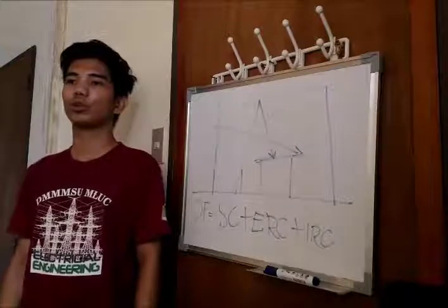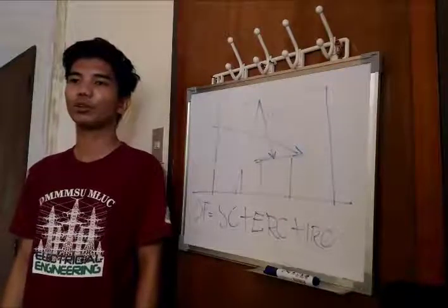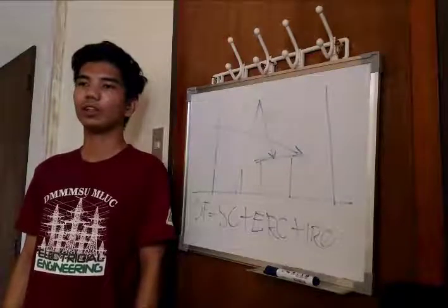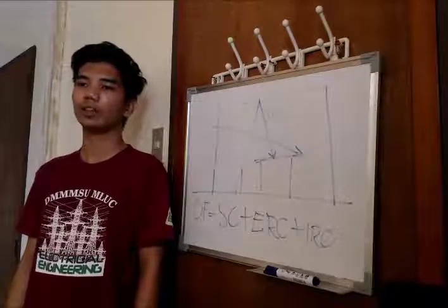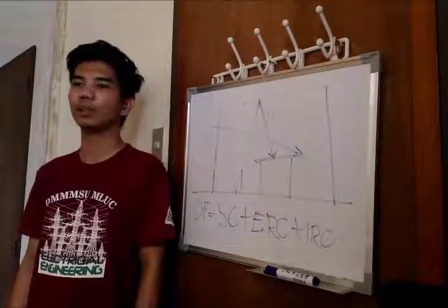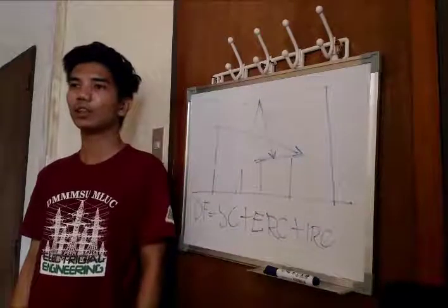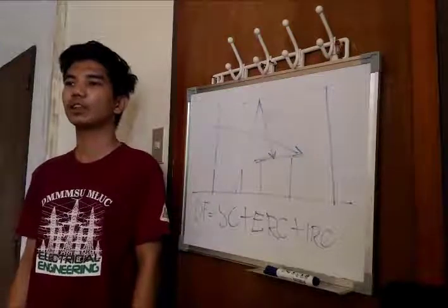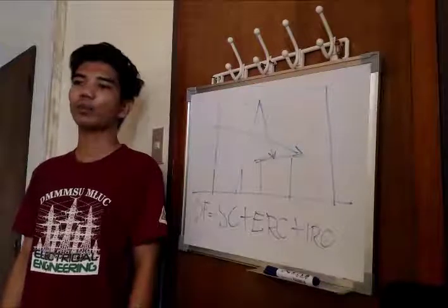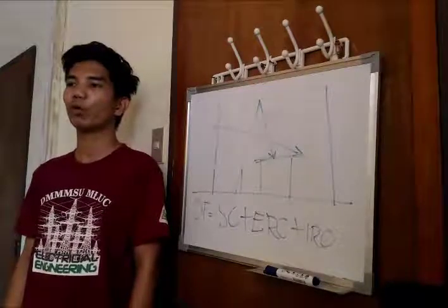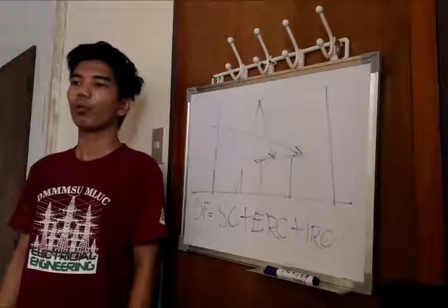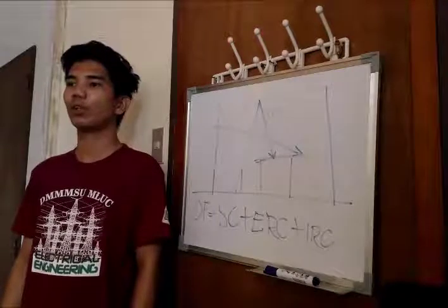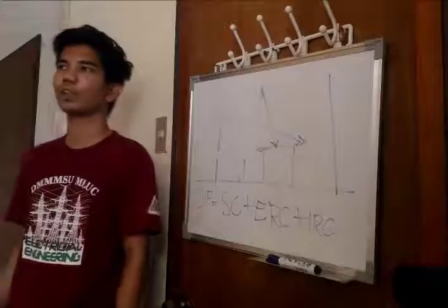What is distribution? It introduces as much controlled daylight as deep as possible into the building interior. The human eye can adjust to high levels of luminance as long as it is evenly distributed. In general, light which reaches us indirectly, such as after a bounce from a wall, will provide better lighting quality than light which arrives directly from natural or artificial sources.